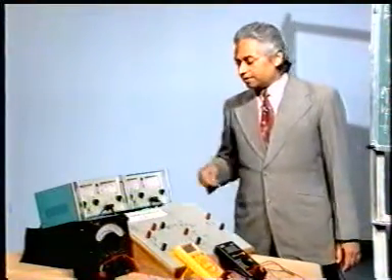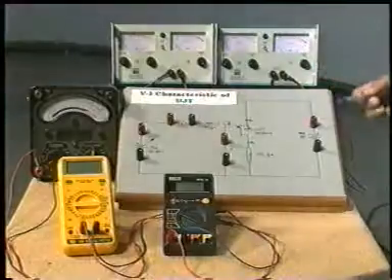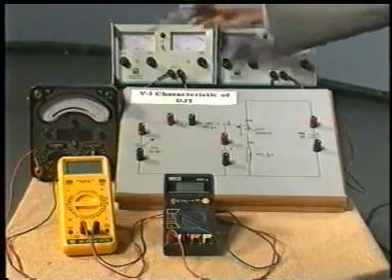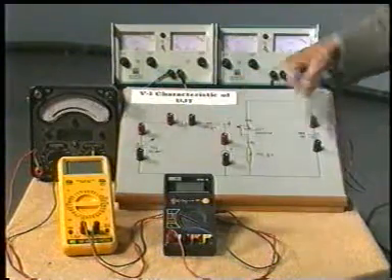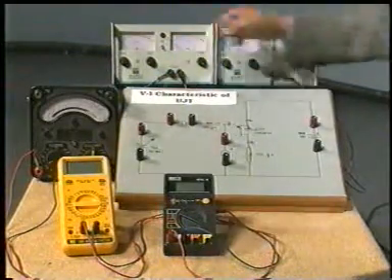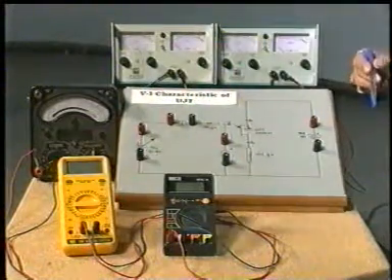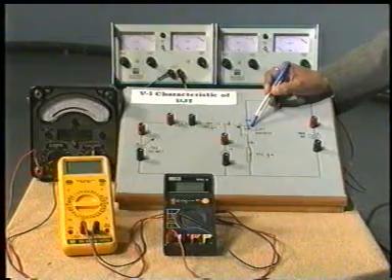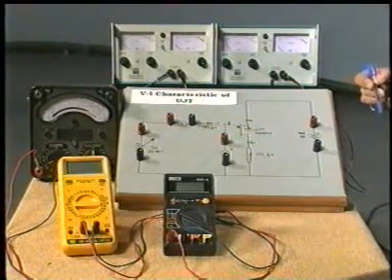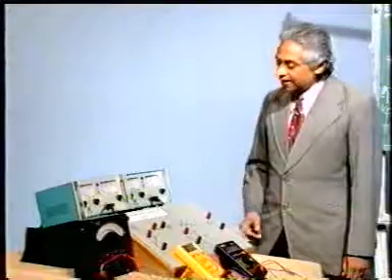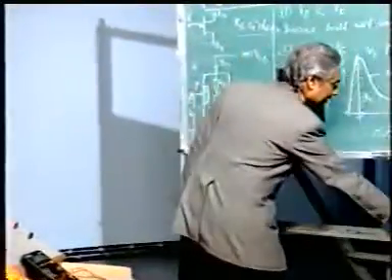So this is the setup before you for verifying the VI characteristic of UJT. As you see, we are going to use 2 power supplies and 3 multimeters for doing this experiment, and of course this is the main board which has the required circuit fabricated in it. Now let me first explain the circuit. This is the main device, which is the UJT, and you see 2N2646 has been used here.